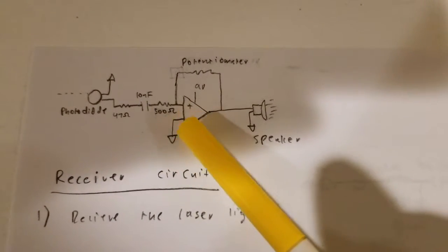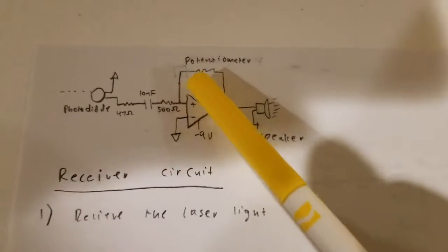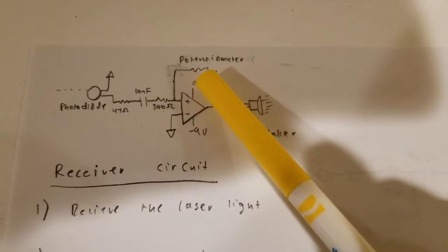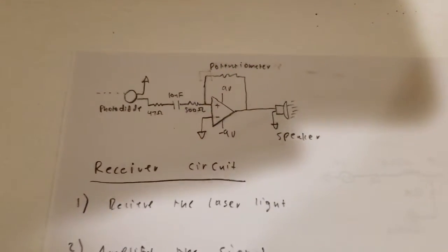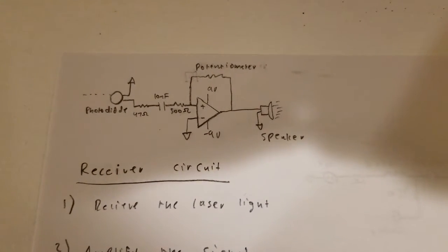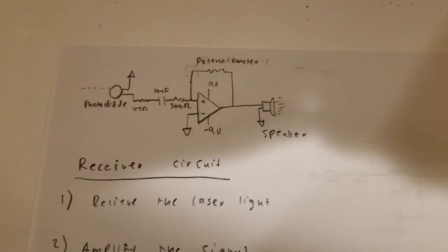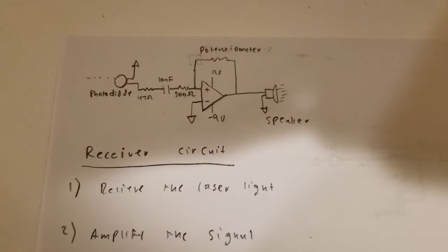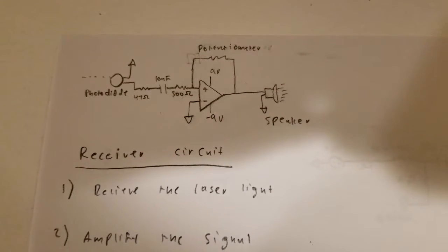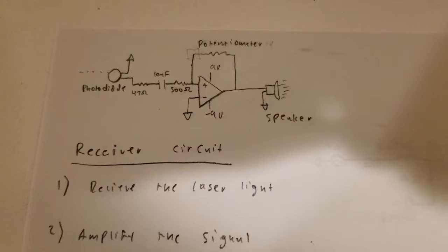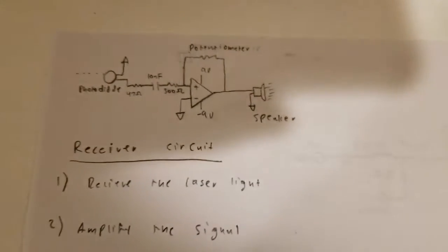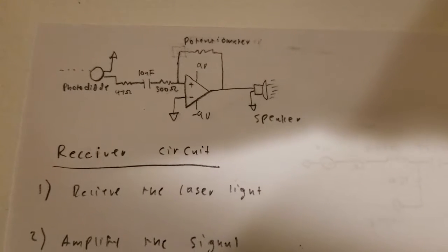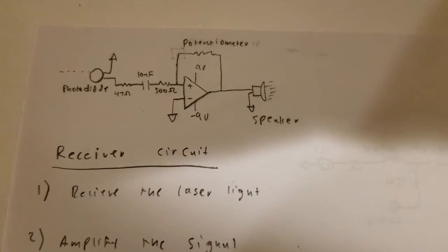After that, we have another non-inverting op amp, but this time the top was a potentiometer instead of a regular resistor, because that allowed for control of the volume going to the speaker. It still acted in the same way because the potentiometer could fluctuate between 1K and 10K ohm resistance, so it acted as a feedback resistor while the other one was just the initial resistor to create a gain. After that, the output from that op amp went to the speaker, all the way to the right, and the speaker was able to play the audio.